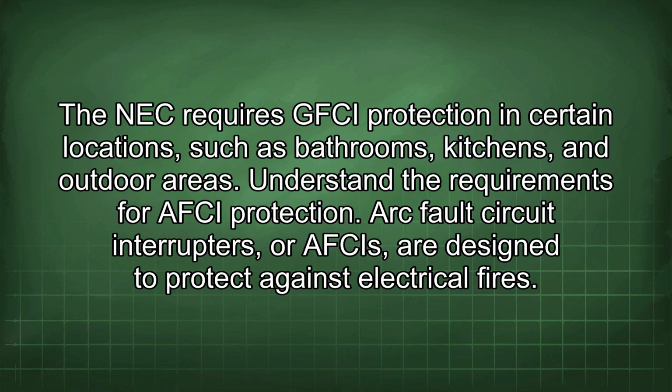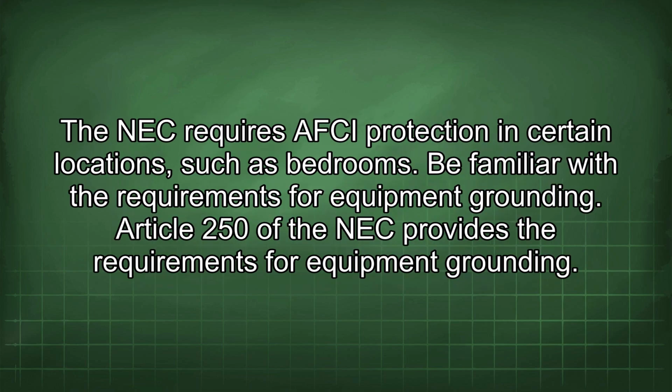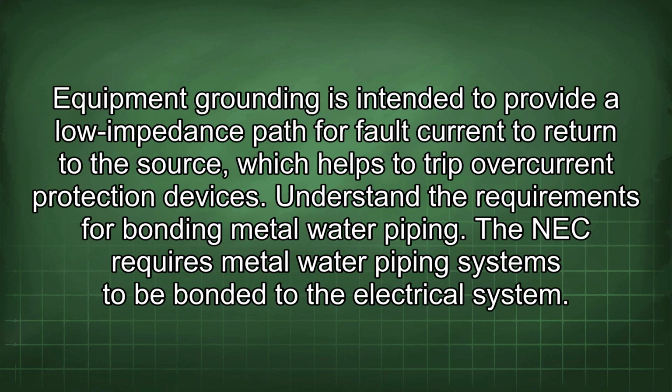Understand the requirements for AFCI protection. Arc fault circuit interrupters, or AFCIs, are designed to protect against electrical fires. The NEC requires AFCI protection in certain locations, such as bedrooms. Be familiar with the requirements for equipment grounding. Article 250 of the NEC provides the requirements for equipment grounding. Equipment grounding is intended to provide a low impedance path for fault current to return to the source, which helps to trip overcurrent protection devices.